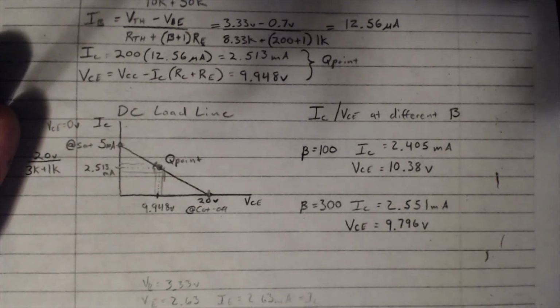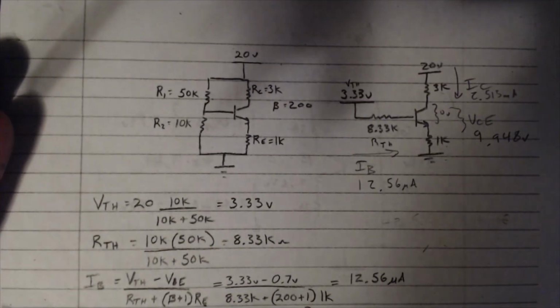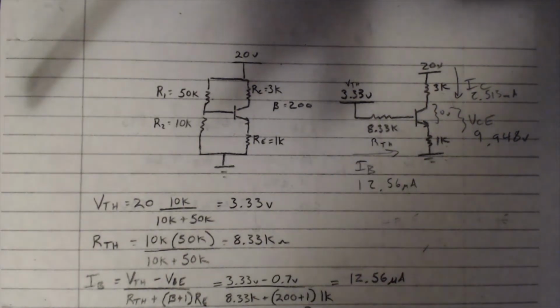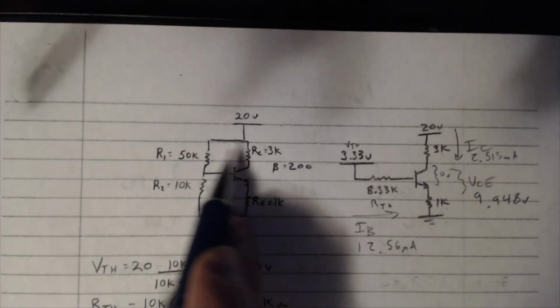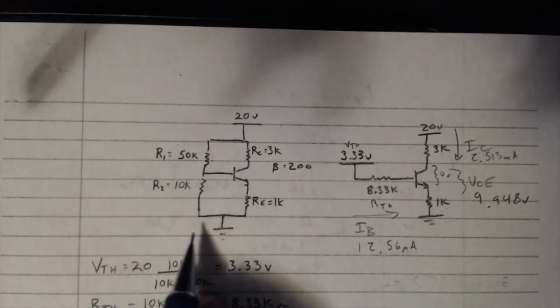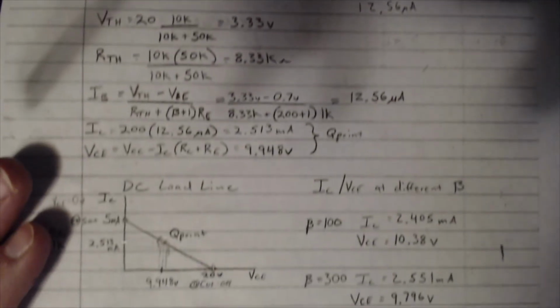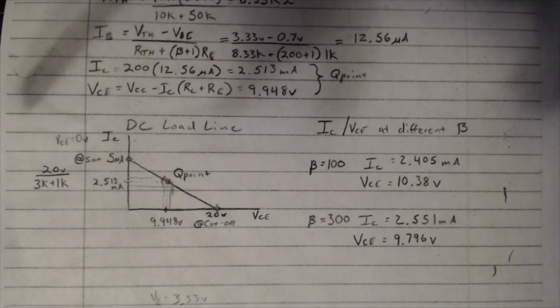And that's why you're going to find that this circuit ends up being the most popular BJT circuit in every single circuit constructed, right? If you're using a transistor, if you're using a BJT, if you're going to make an amplifier, you're probably going to see this. And that's the reason why, because this very much doesn't care about changes to beta.